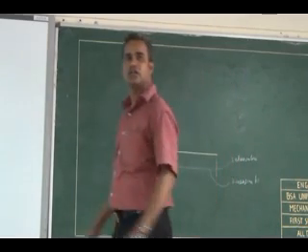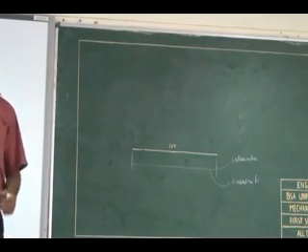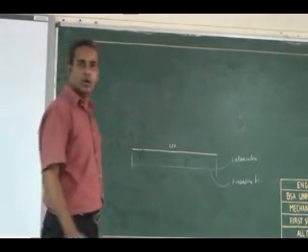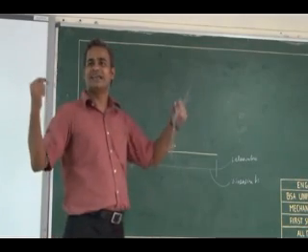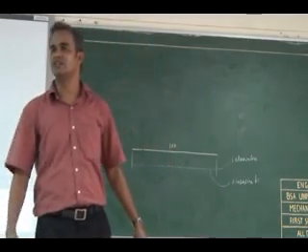This is another entity in dimensioning. Then I have to show my arrowheads. Touching the extension line. The arrowhead should touch the extension line, and it should not extend beyond the extension line.